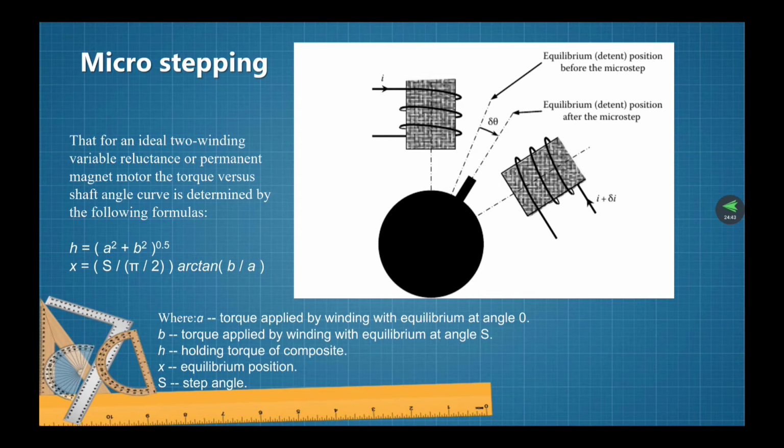In both cases, the current level or state of a phase is either 0 or 1, rather than using just two current levels, which is the binary case. It is possible to use several levels of phase current between these two extremes, thereby achieving much smaller step angles. This is the principle behind microstepping.